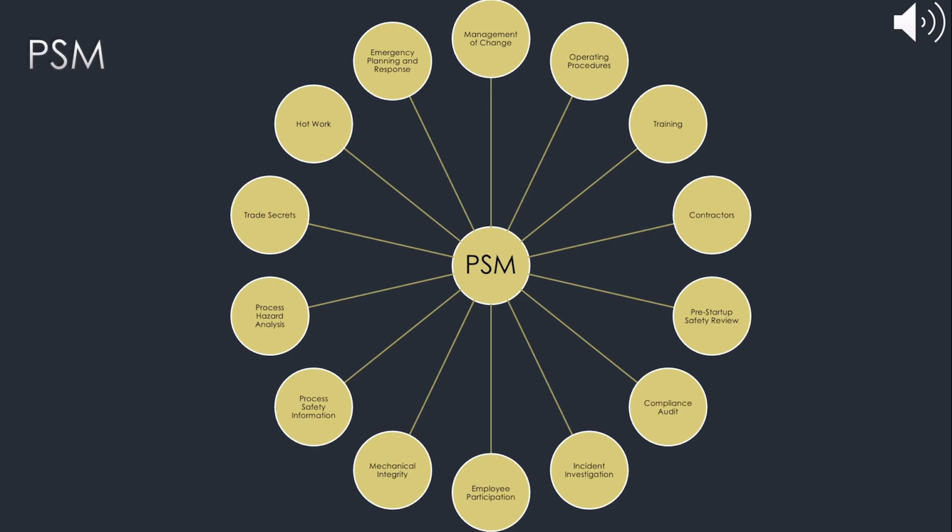The pre-startup safety review must be conducted for new and modified facilities before operations can begin. Compliance audits must be conducted and reported at reasonable intervals. Thorough investigations must be completed any time there is an incident associated to the process.